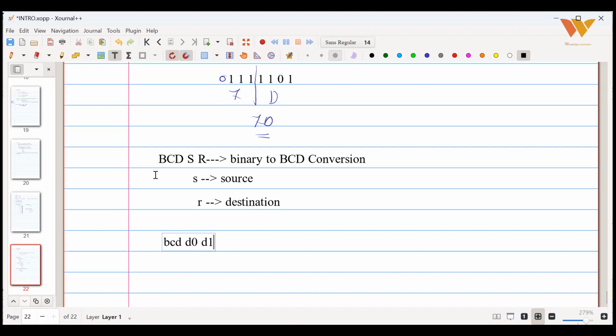Ma'am, difference between byte memory and bit memory. 1 bit, that's all. 1 byte will be 8 bits. Only this much is the difference. Whenever you have arithmetic or alphanumeric values you want to store, we'll go for this register. If you want to store only a high or low condition, we'll go for a bit memory.